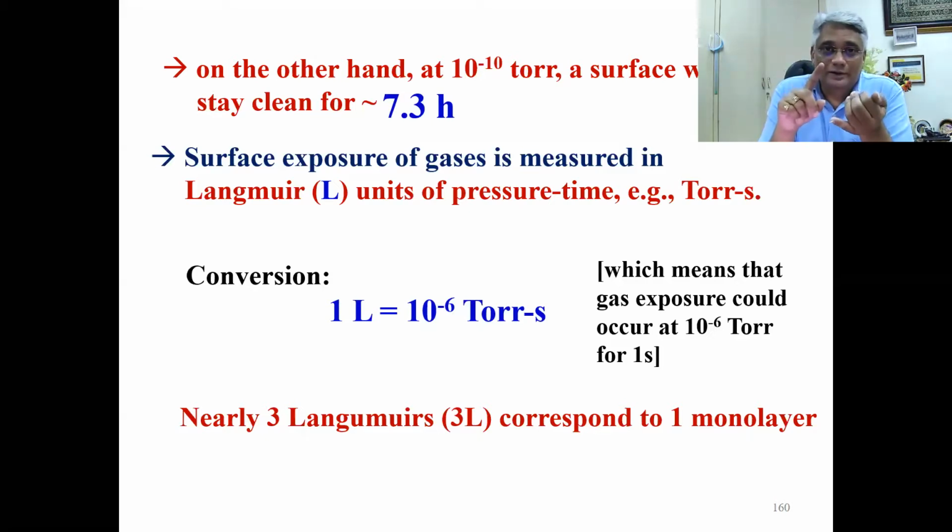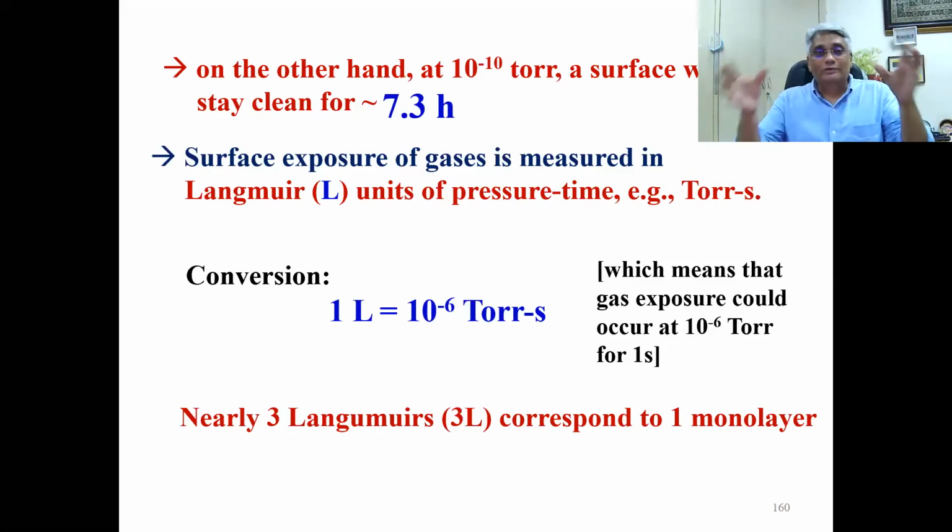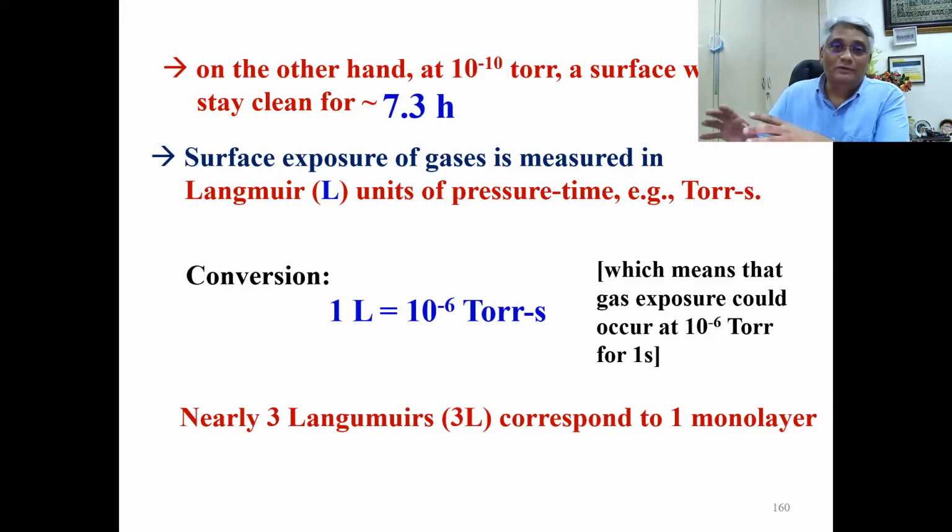So it's for keeping the surface clean so that the thin film deposition is perfect in terms of getting only those atoms. I don't want any other set of atoms between the substrate and the atoms of the thin film. If I have a different set of atoms, that means I have an impurity. For analytical experiments, again, you have used a very sophisticated experimental technique, and then you think you're done, you want to transfer it to a surface analysis technique, but again made a mistake of not keeping it in vacuum before you transfer it to the surface analysis unit. You've already contaminated the surface.